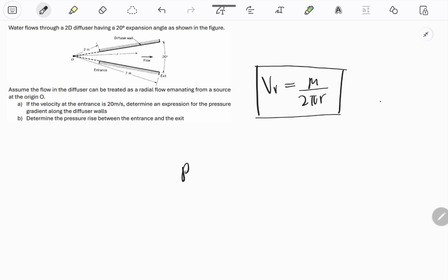Bernoulli said the pressure in plus 1 over 2 density V squared should equal the same thing as you go to the other side. So let me say it should be constant, right? Because it could be in and out, or maybe in plus another 3 out if there are more exits and all that. So the question, let me read it before.